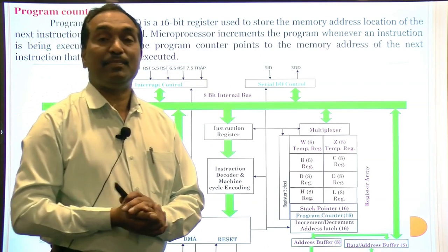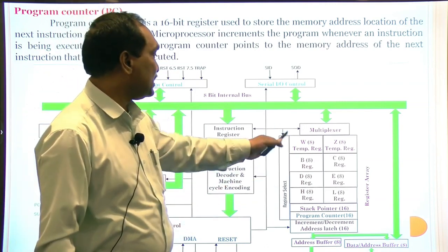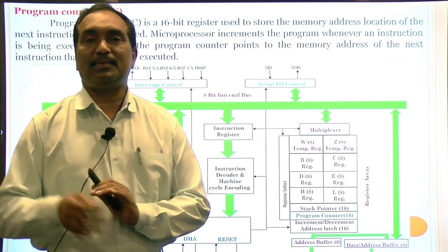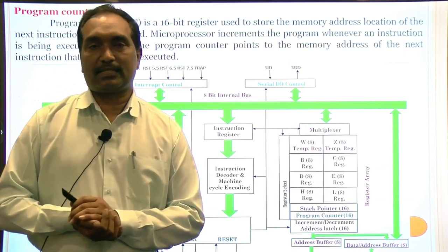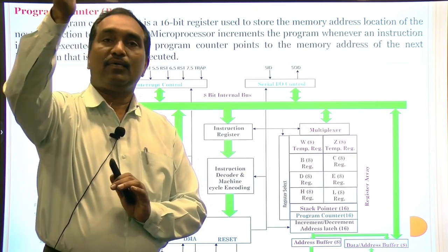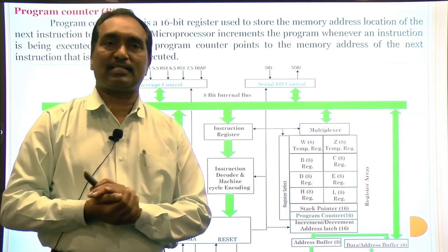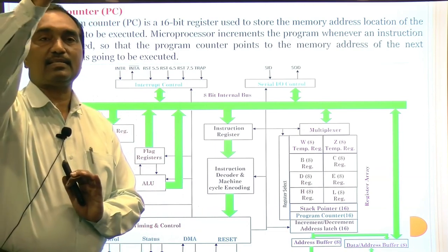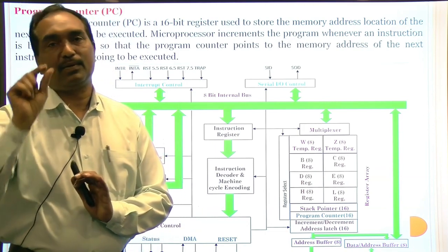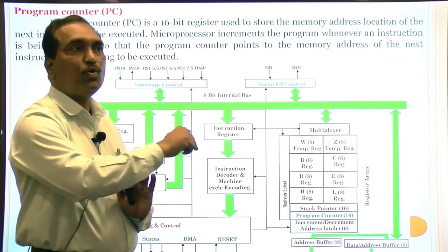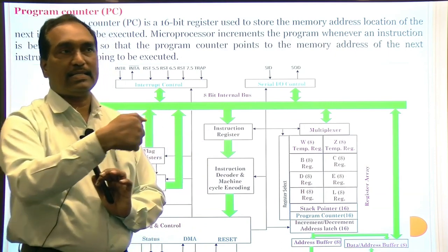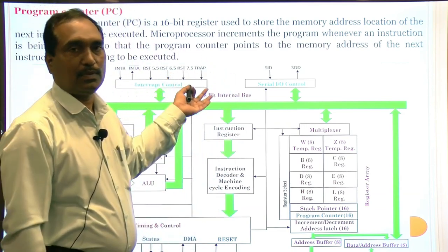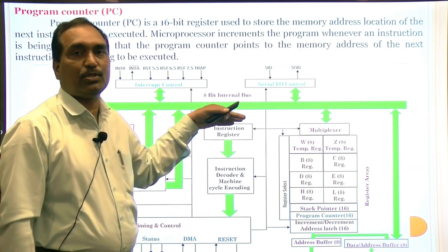And another number, 6, can be stored in a register, that may be B, C, D, E, H, L, whatever it is. There is MVI C, 6, that is, the number 6 is stored in register C. So the first instruction is MVI A, 5, and MVI C, 6 is the other instruction. The first instruction can be given one memory location, say 8000, and MVI C, 6 goes in the next location, 8001.